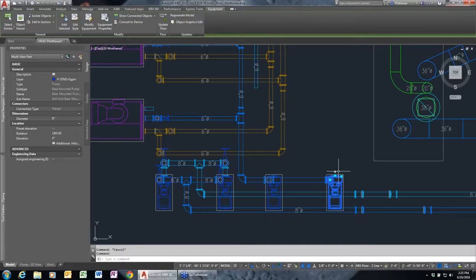The difference between a pipe and a plumbing line in AutoCAD MEP is a pipe actually will be modeled in 3D with 3D geometry and 3D space. The plumbing line is really more of a schematic representation. So often when people are doing plumbing layouts, especially in the past, though today people are actually starting to model pipe plumbing, you can just use a schematic plumbing line instead.